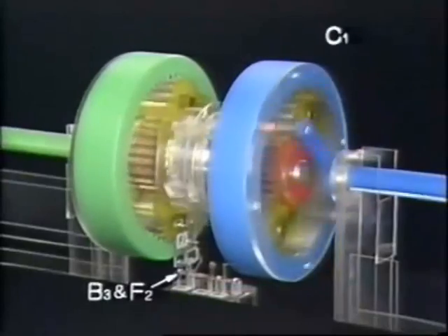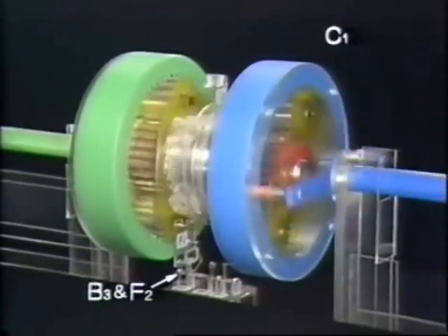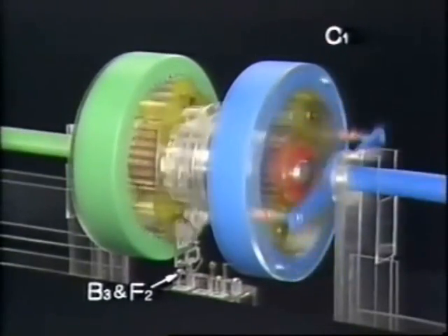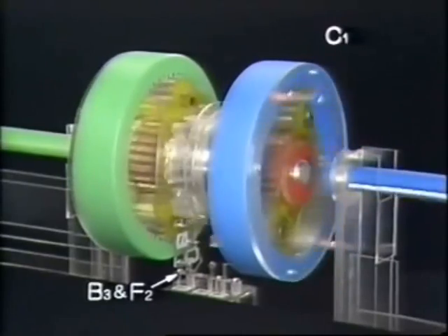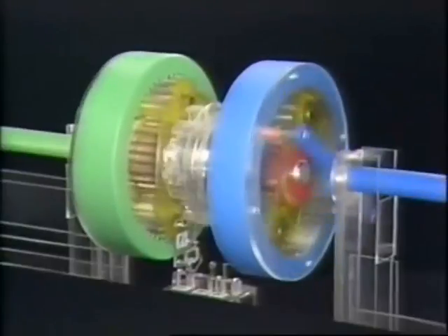In first gear of the L range, both the front and rear planetary gear sets are actuated, as in the case of the first gear of the D range. But brake B3 prevents the rotation of the rear planetary carrier in either direction, and engine braking occurs as a result.